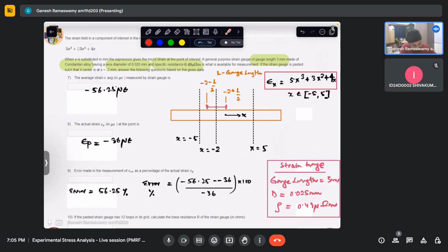So what this implies is at this point, if the strain variation is very high, then the average strain that we are trying to capture may be off by the peak strain by a significant amount. As we see here, it is almost 50% off. The question naturally does not say what is the application, whether it is just a first level analysis, because for a first level analysis, even a factor of this is acceptable in certain cases. So it depends on the application, but that is not the focus here. The focus here is to see how to mitigate this issue. If we need to refine our results, how to go about doing that.